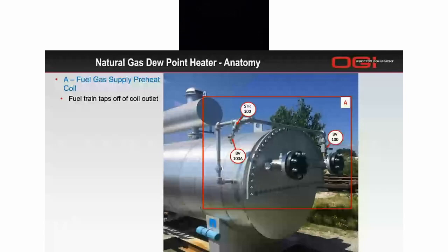So we're going to follow this along, and the gas train comes to the next major component. That's the strainer, the STR100. The strainer is kind of a filter. There's not a micron rating to it per se. It's just getting any larger contaminants or particles that can come into play and could damage any components. There is a ball valve, BV100A, mounted on this strainer, so you can isolate and drain, and then remove the screen. The screens are typically cleanable or replaceable, whichever. It kind of depends on how much contamination there is.